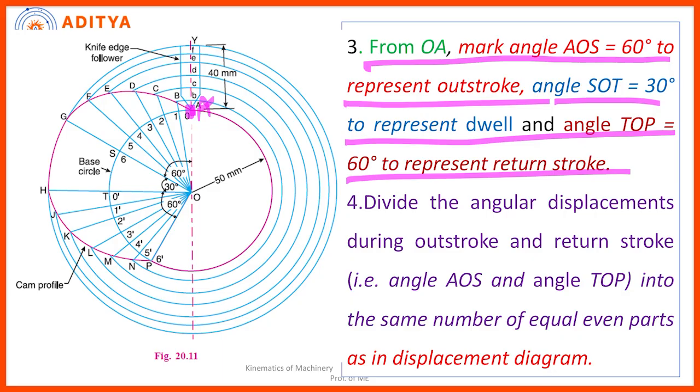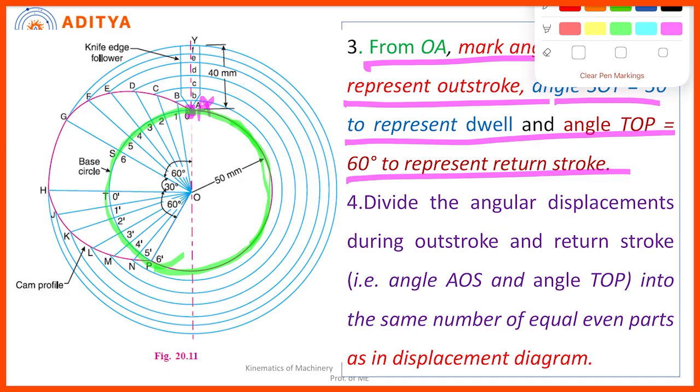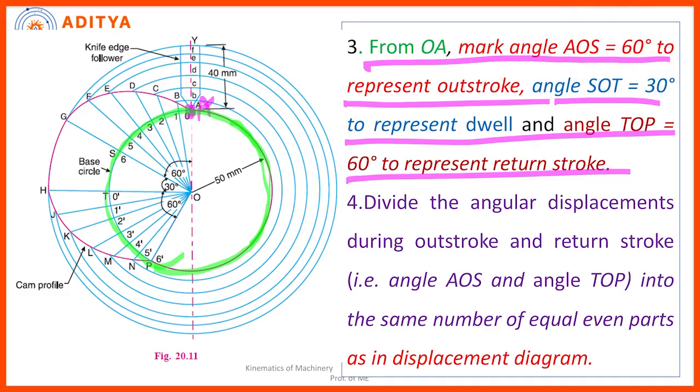Okay. This is actually the circle. So initially we don't have any other things, I am having only the circle and point A, right. Now in the displacement diagram, what you made, you divided this 360 degrees into some parts. What is the part 1? Now whatever the cam rotation angle, the same rotation you need to transfer to the circle. So 60 degrees, you draw a 60 degrees point, put the point S on the circle, right.